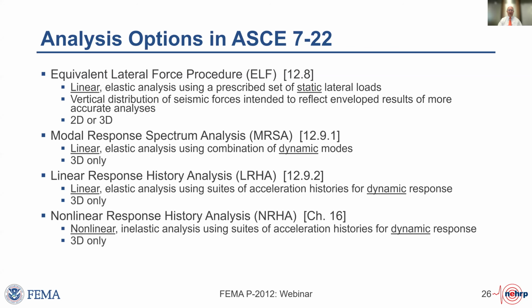Modal response spectrum analysis takes that same model or models perhaps and does something different. We still consider the structure to behave linearly, so using linear elastic analysis, but then we think about some dynamic response in a modal sense. That method can only be done 3-dimensionally, so we can't use 2-dimensional characterizations of our structure to use this method. The next step up would be to use linear response history analysis, where we actually select suites of ground motions.